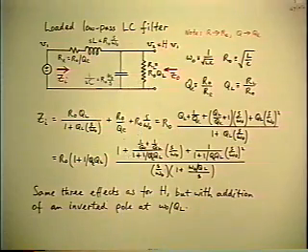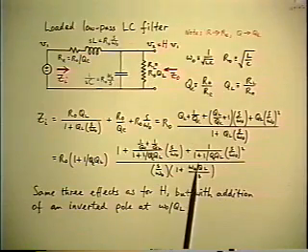So there is a change of asymptote slope as you go towards 0 frequencies, depending on whether or not the load resistance is there. If there is a change of slope, then there must be an additional corner frequency. And the inverted pole is the frequency that describes that.